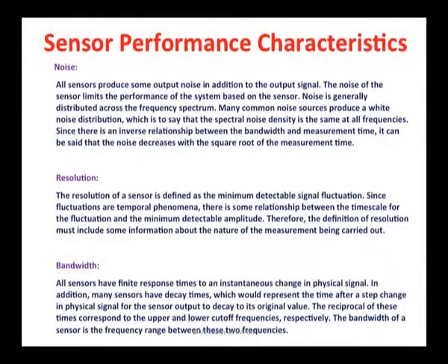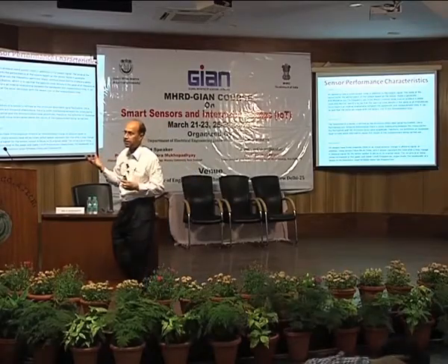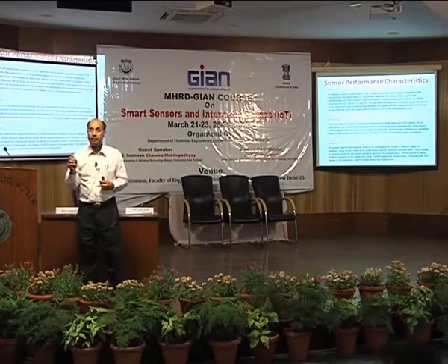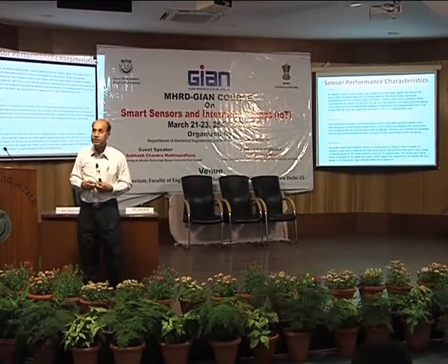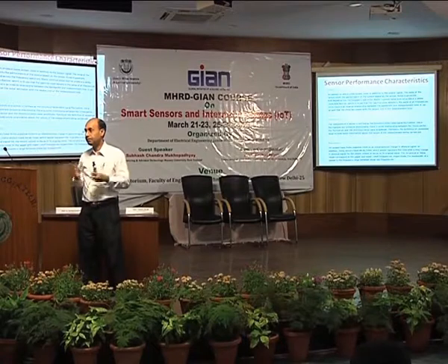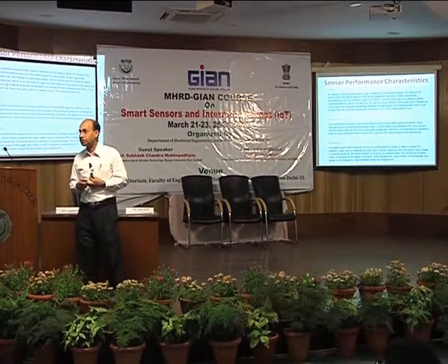That's the frequency band within which your response is constant. That's the bandwidth. Bandwidth is very, very important when you have electronic circuits like an op-amp in your circuit. Because if you do not know the bandwidth and you operate at a different frequency, you may get a completely different result. You understand?